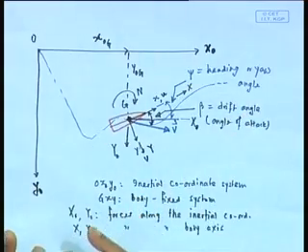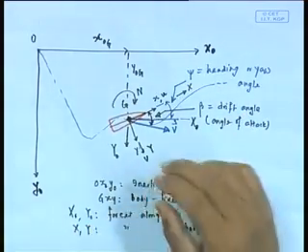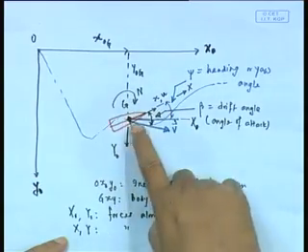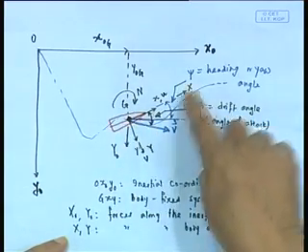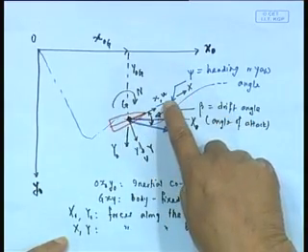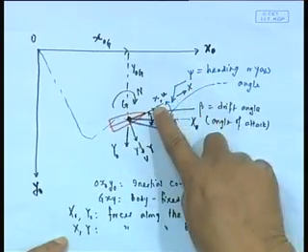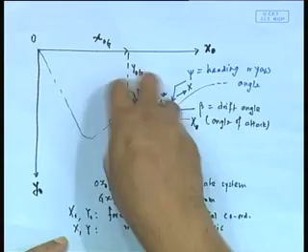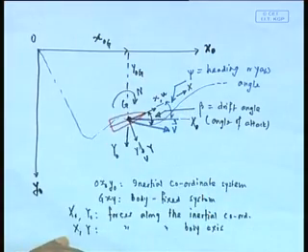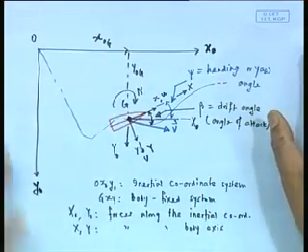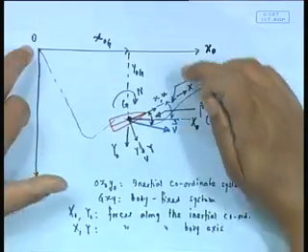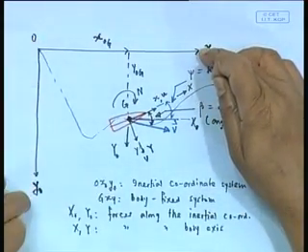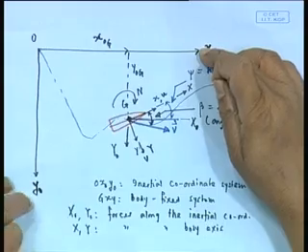I need to write an equation of motion. Remember, I cannot write it with respect to this frame by simply saying that the x force equals mass into this acceleration, that is X equals m into u dot. I cannot say that, because this body is rotating also; it is a rotating frame of reference. You probably know this from kinematics. Essentially I have to write this equation of motion in the inertial frame of reference, because in this frame there is no rotation.